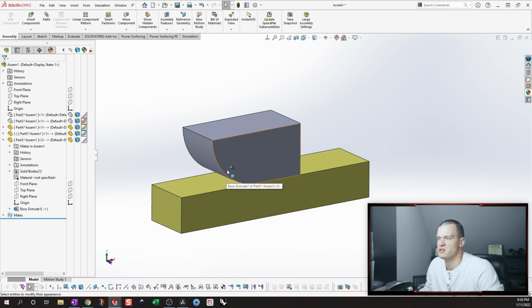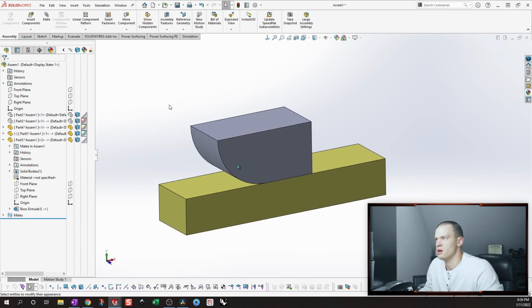We'll be able to put a sketch for the reference for the slot into the part, and then it'll be within both the red part, the original one, and the copied one, because they're really the same part. So you can pass information back and forth between the two, even though you have them in different positions. And so that's one of the keys of this method.